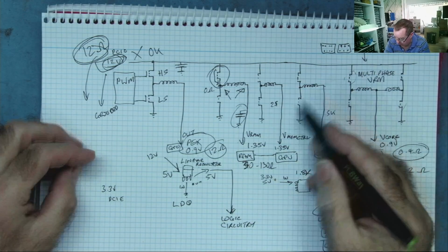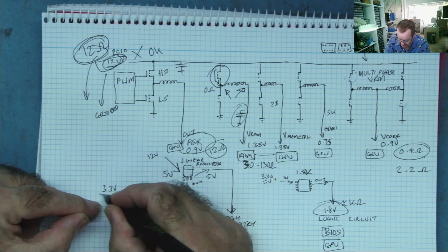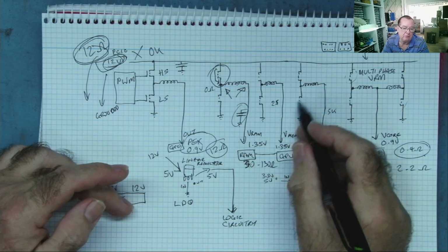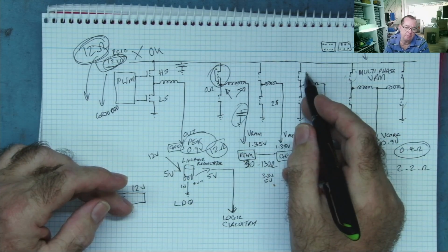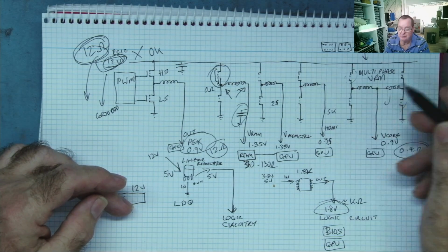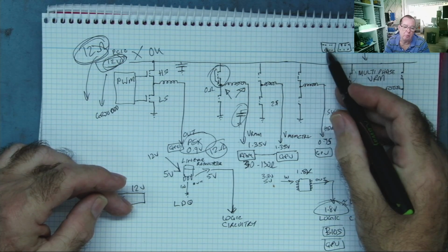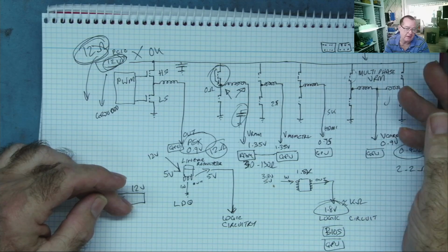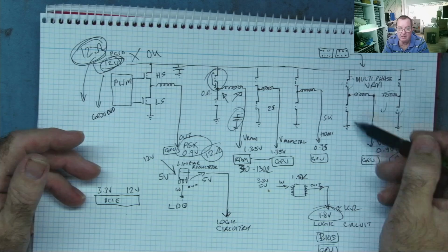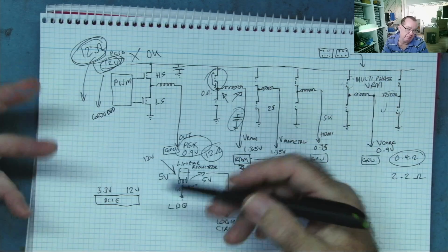But the RAM, for example, may be coming from the 12 volts on the PCIe connector, okay? So you can find a situation where this is running one of these buck regulators or converters, and those are running another. You can have situations where you may have 8 of these phases, and 4 of them run off one connector and 4 run off the other connector, and so on. And I've also seen situations where there's multiple phases here, and say 4 of them run from here and 2 run from here, and this sort of thing.